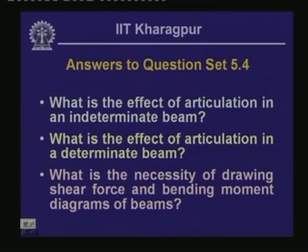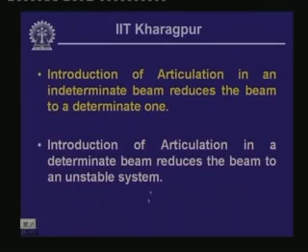Now, the third question is, what is the necessity of drawing shear force and bending moment diagrams of beams? You have gone through the previous module wherein we have discussed various kinds of loading on various kinds of beams, and then we have evaluated the shear force and bending moment at different sections. As you have seen, if we need to know the variation of the shear force or the bending moment along the length of the beam, then if we draw the diagram over the length of the beam, the variation of the shear forces at every section, it becomes easier to appreciate which part of the beam is subjected to what kind of shear forces or bending moments.